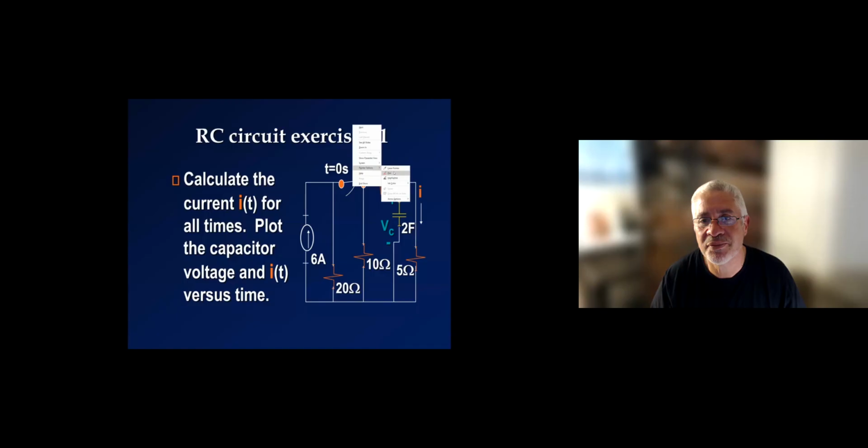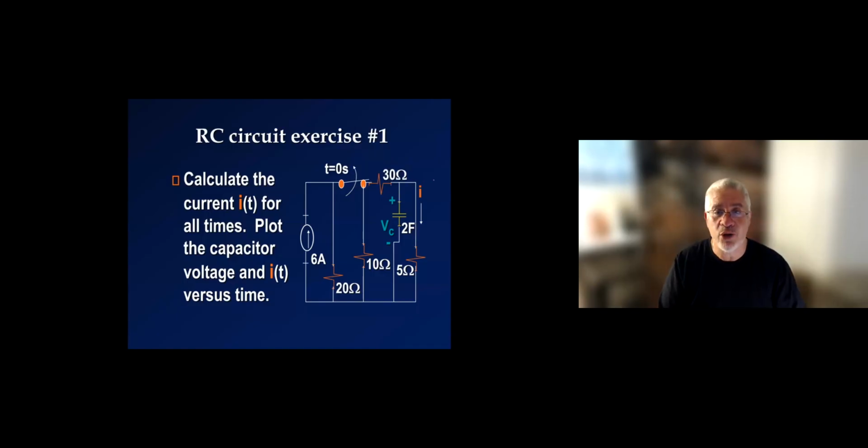So we're looking at a circuit here. Let me summarize where we are. We are looking at first order circuits. First order circuit means what? A circuit with either one capacitor or one inductor. Generically, I'm going to say one energy storage element. Capacitors and inductors are energy storage elements. And we are focusing this introductory lecture on circuits that have zero input. So we typically have a switch that disconnects at some point, in this case, t equals 0.